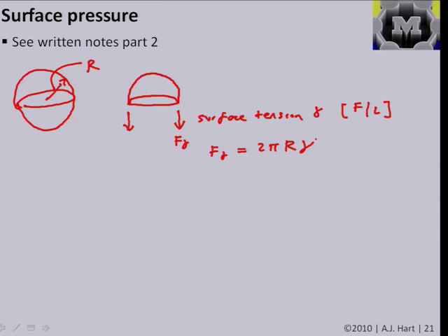And so if this body is in equilibrium, it's sitting in some atmosphere with some pressure. So we have pressure on the outside, which we'll call P outer, and we have a pressure on the inside, which we're going to call P inner. So for this body to be in equilibrium, we want to sum the forces on it and have the forces sum to 0. And if we take, for example, forces in this direction downward to be positive, we have the surface tension force being positive, so 2 pi r gamma.